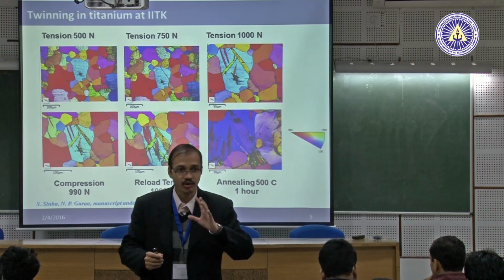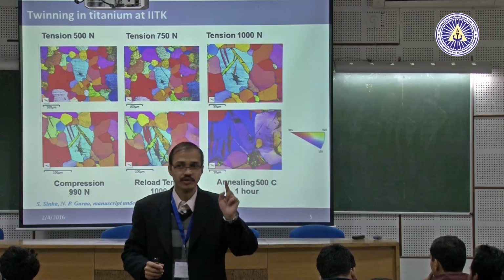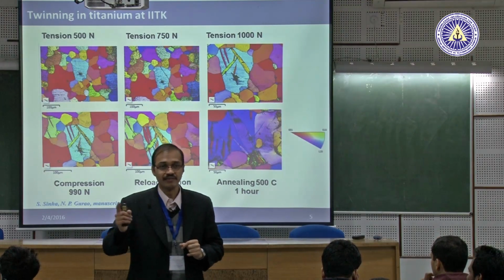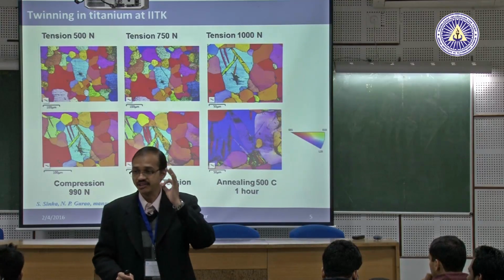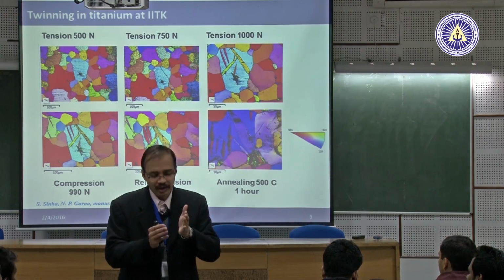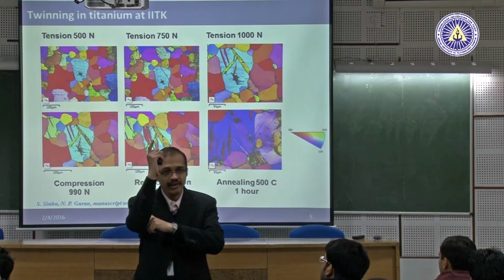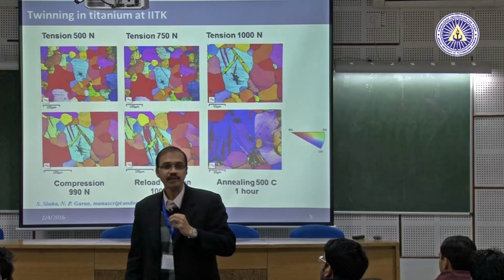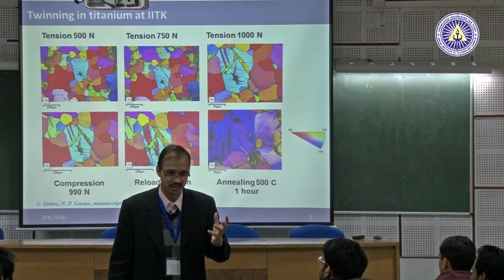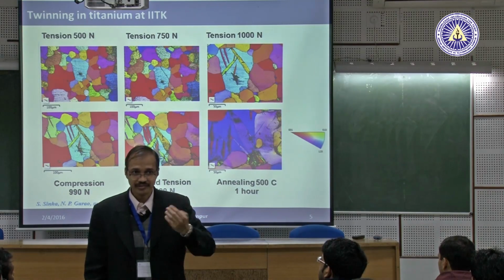Not all the grains get elongated the same way, depending on their orientation. Professor Unger mentioned that if you take a single crystal of copper along 100 and 111, the elastic moduli differ by 3 times. Except for a few niche applications like superalloys, where you have a blade which is a single crystal, you generally tend to use polycrystalline material. So polycrystalline material is going to be an average.